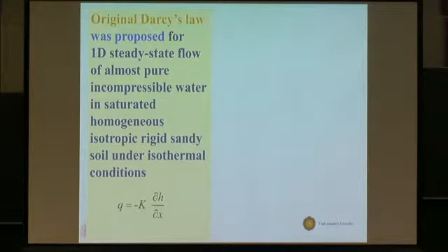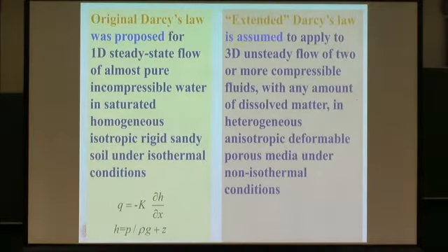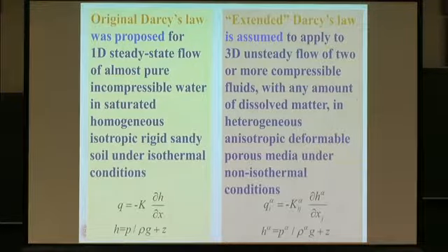It's a linear relationship. And the hydraulic head is defined as pressure head plus elevation head, and now it's assumed to apply to 3D unsteady state flow of two or more compressible fluids with any amount of dissolved matter in heterogeneous, anisotropic, highly deformable porous media under non-isothermal conditions. See how many more processes are added. And of course, then Darcy's law applying to this system must be much more complex than the other Darcy's law, right? Wrong. It's exactly the same. There are some indices added, but the driving forces, the relationship is exactly the same. The head is also defined in the same manner.